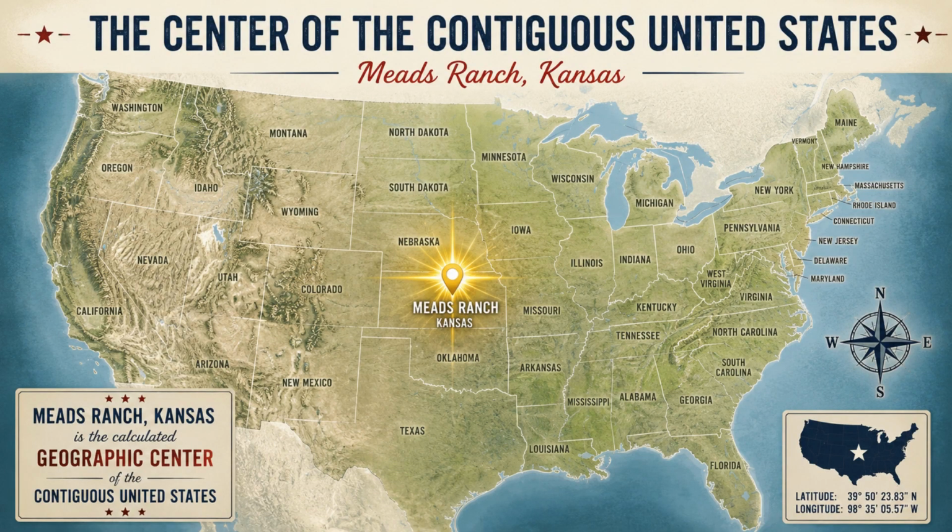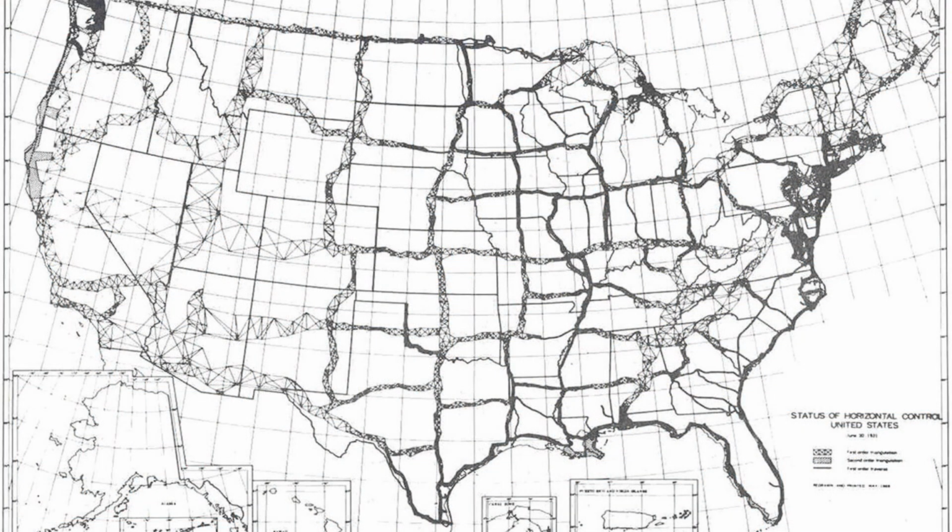I know, it sounds arbitrary today, right? But before satellites, regional surveyors used optical triangulation. Like literally looking through instruments from hilltop to hilltop. Exactly. They needed a physical starting point roughly in the center of the contiguous United States. So they aligned the mathematical ellipsoid so its surface perfectly matched the physical geoid right at that specific spot in Kansas. And from there, they triangulated outward.